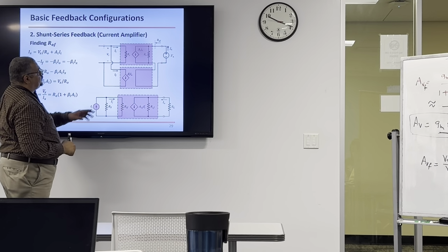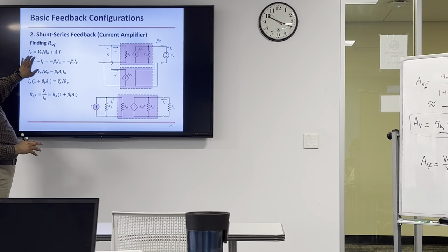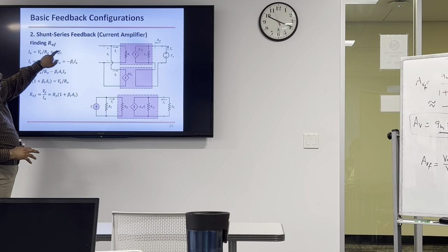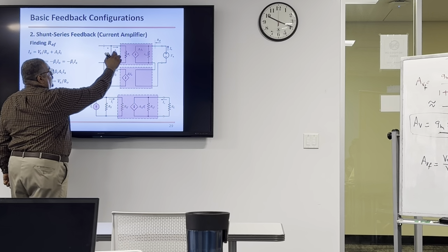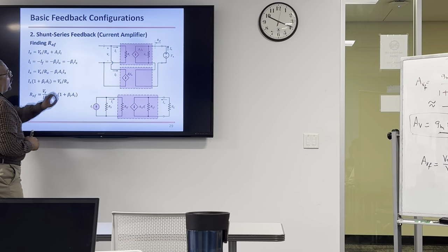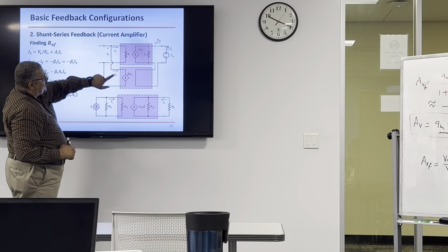Now let's go to the Ii. We need to find an equation that links Ix and Vx only. Now this equation has Ix and Vx. This is constant, but this is not a constant. We need to get rid of this one. Now let's go to that input circuit. Ii is what? If you open circuit here, then Ii and If are going to be the same, right?